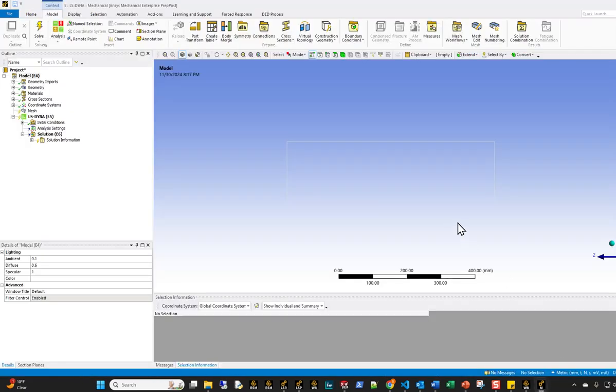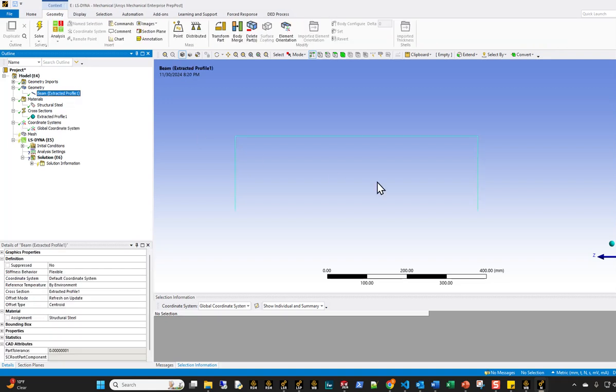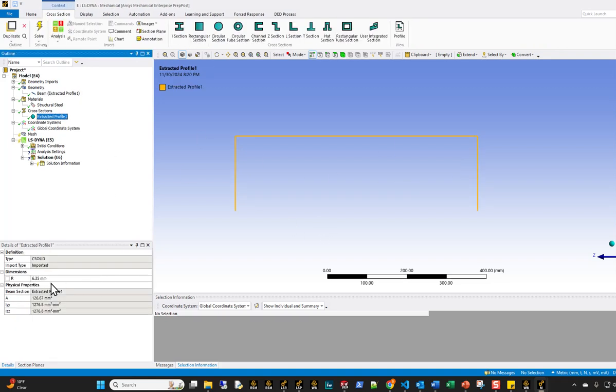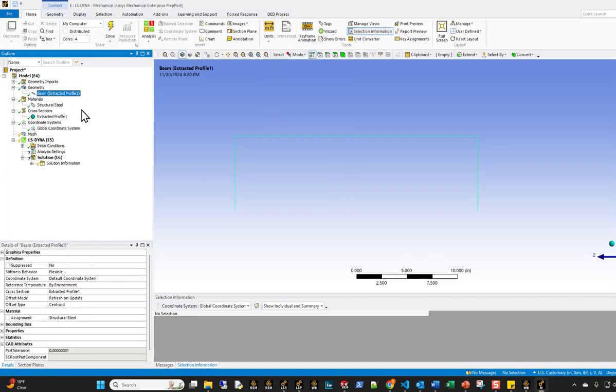All right. So in this model, you can see I have just a single body with a 0.2 width or so around here. Let me change this to inches. But about a quarter inch of beam cross section in here. The cross section is really not relevant because I'm mostly doing it for demonstration of the pulley action. The way we're going to do this is, first of all, let's go ahead and mesh the beam.